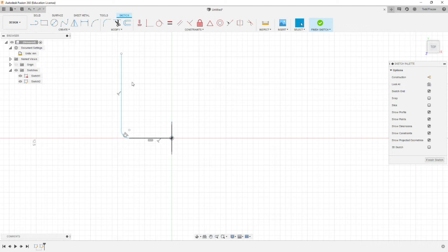Okay, so this represents the center line of our part. And you notice this line and this arc didn't end up being tangent. So I'm going to go back and create a tangency between those. Okay, now we're ready to dimension. So our drawing says from the bottom point of our tube to this end point here is 31.15. We're going to dimension it from the center line, so we need to subtract half the diameter of the tube from that number. So it's actually going to be 30.